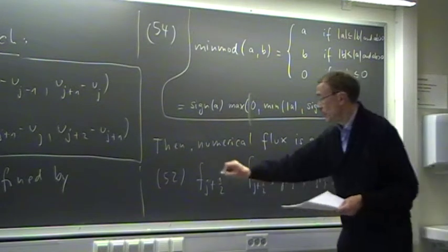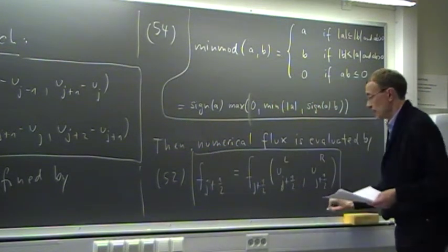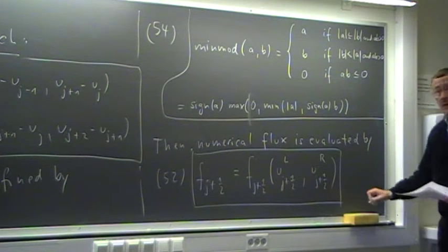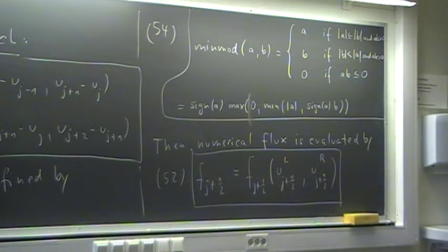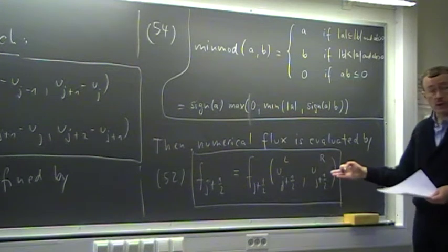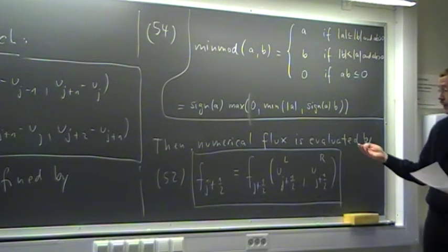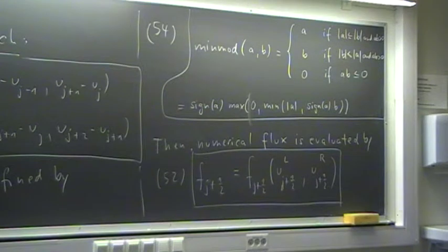And then we do that also again, as I mentioned also last time, when we compute the fluxes beforehand. So we compute all fluxes that we need, and then when we use that in the conservation form, we have it available, and we do not need to evaluate the fluxes twice that we would have to do otherwise. Because the flux that goes out on the right is entering the cell on the right as left flux. So if you have calculated that once, it is just a different sign, but the values are the same. So that's the idea.